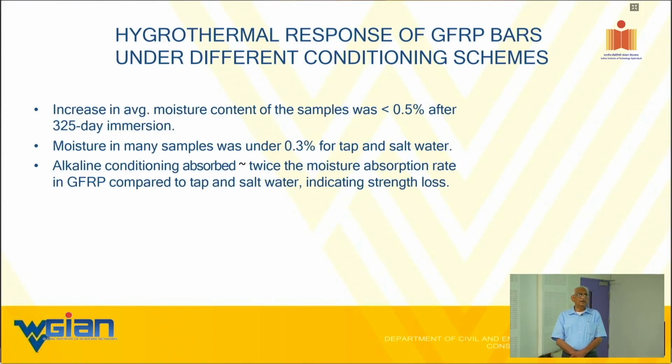We made bars with polyester by pultrusion, but we have done a compression molding on top of the bar with ribs using polyurethane. That's a cheaper process than the vinyl.